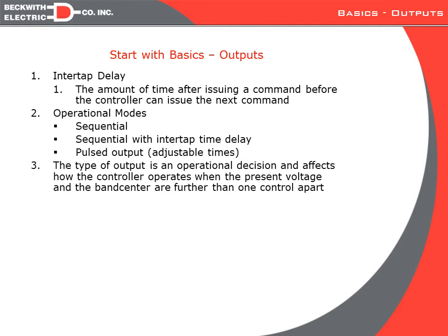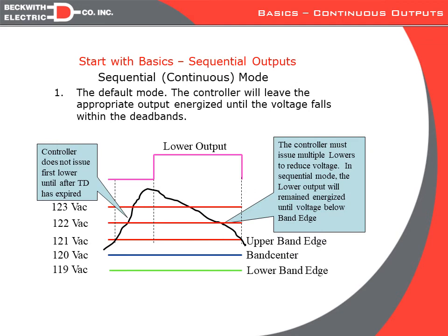We're to the final part of this session, and that is we have exceeded band, and we've exceeded band for longer than the time delay. At this point, it is time for the regulator to take action, and the control needs to send either a raise or a lower command. To do that, its physical output will be interfaced to the motor in some form or manner to the regulator or LTC, whether it's spring charged, whether it's direct driven on the motor. We need to get an output to drive the mechanism of the regulator or LTC to take a physical tap.